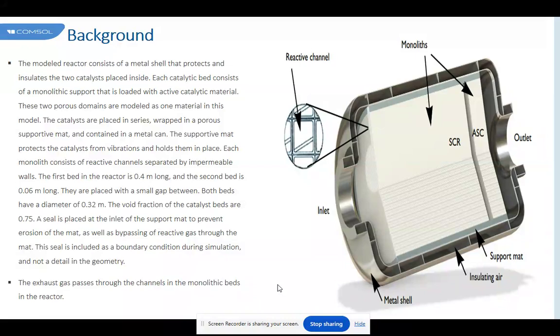Positive results are also observed. We remark specifically on the case when the core and ring have the same volume. The two combinations 900 C per 400 R and 400 C per 900 R lead to the same pressure drop, but in the latter combination the CO depletion is 50% higher. This improved trade-off between back pressure and conversion efficiency shows the potential for monolith shape optimization by using heterogeneous cell densities. The most notorious and direct effect of using a heterogeneous cell density was a largely uneven fluid distribution.